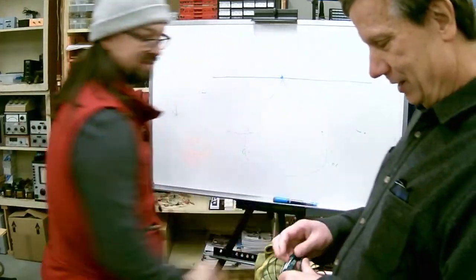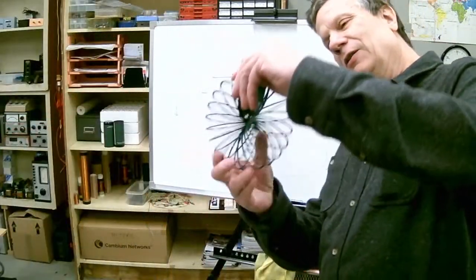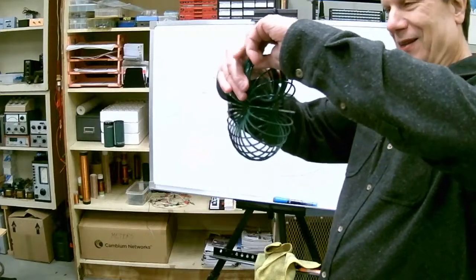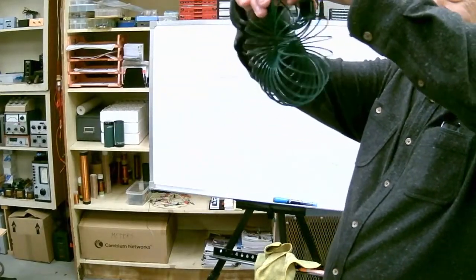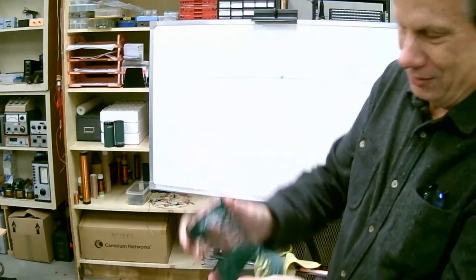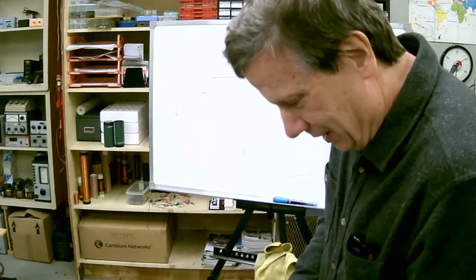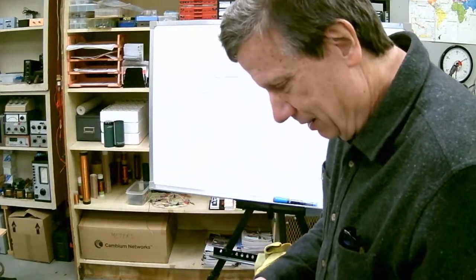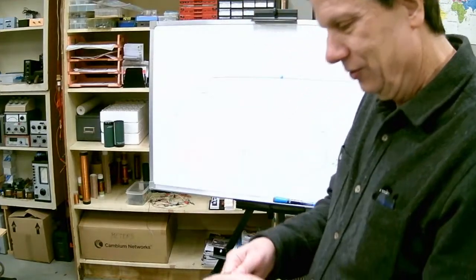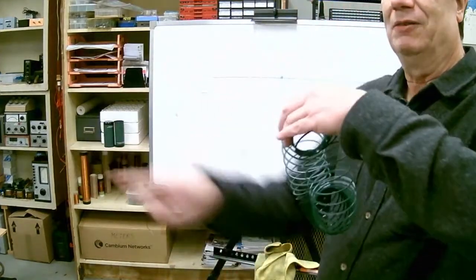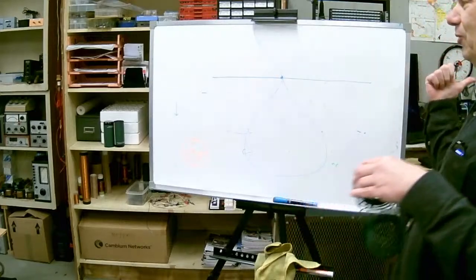What it's going to look like is a little bagel with a point converging in the middle. So that's the radiation pattern of a dipole. One of the important things is there's absolutely no radiation in the line of the antenna itself. Absolutely nothing out this way.